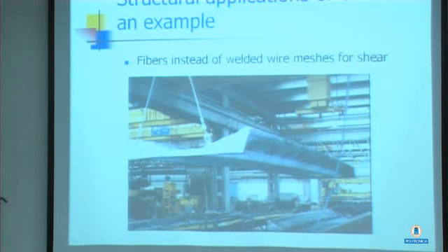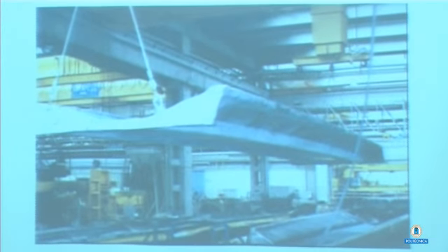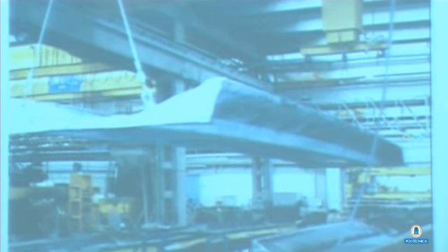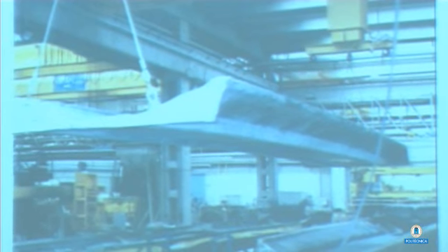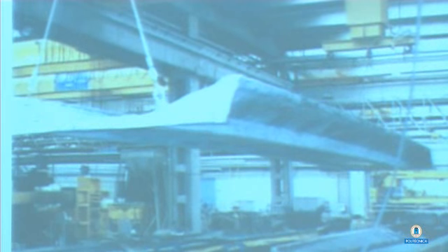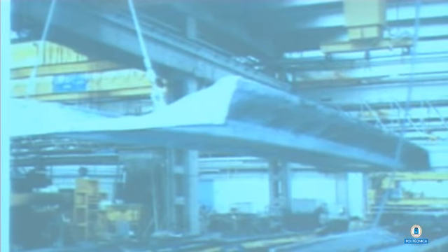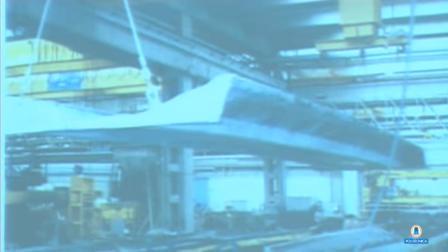This is an example of a precast pre-stressed roof element. They are quite widespread all over the world, let us say, for roofs in industrial buildings. And we had a joint project some years ago with a company and with the Ministry of Higher Education in Italy related to the use of fibers in this kind of elements to completely replace steel reinforcement versus shear and also versus transverse flexure, which can be a problem, while the longitudinal behavior is still guaranteed by pre-stressing tendons.